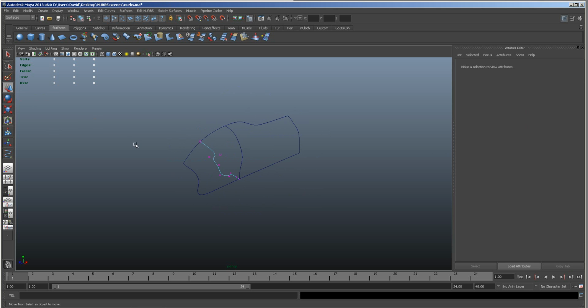Yep, so I hope this course has been helpful to you. It's a basic course on how to set up Nurbs curves for lofting and for using the powerful Byrail technique. There's other tools in here, but those are the main ones that you use if you're creating hard surface models. And we also covered how to convert it into polygons from the Nurbs patch, and also how to reverse the curve direction, how to rebuild the curves to make sure that your parametrization is correct across the curved surface.